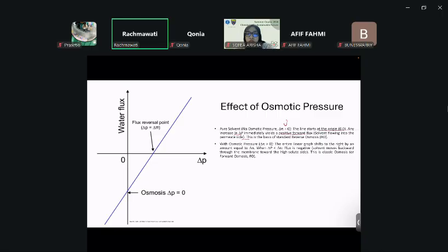So now you have osmotic pressure. It's a colligative property, so it's only affected by the number of solute particles. It is not affected by the type. Whether you have a neutral one or a charged one, as long as the number is the same, the osmotic pressure stays the same, because that's the basis of colligative properties. So now what you have is a feed solution containing solutes that you want to filter off, so you do know that there is osmotic pressure.